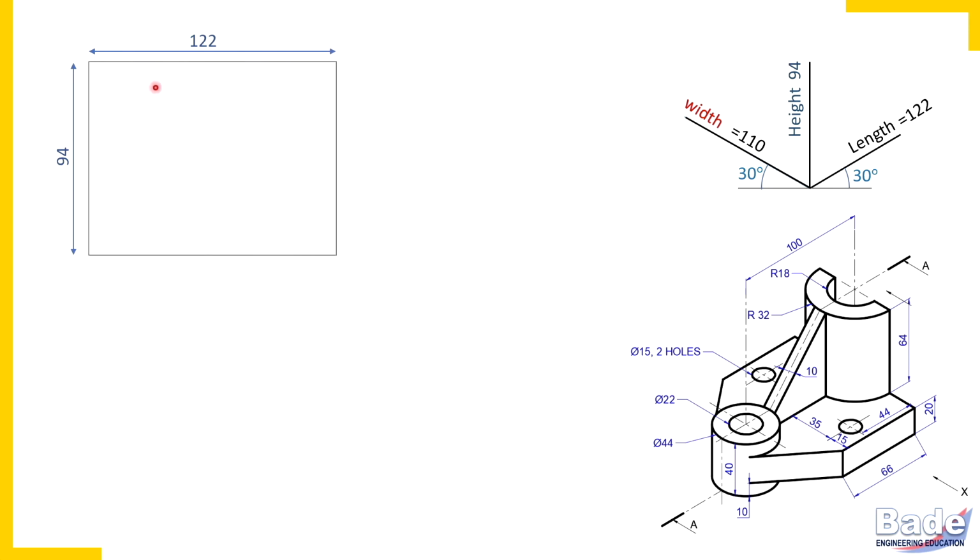Now since we have measured length 122 already in the top view, we need not measure length 122 again. In fact, you must not. You should project that length 122 millimeters in the top view. Which two dimensions do you get in the top view? Correct. Length horizontally